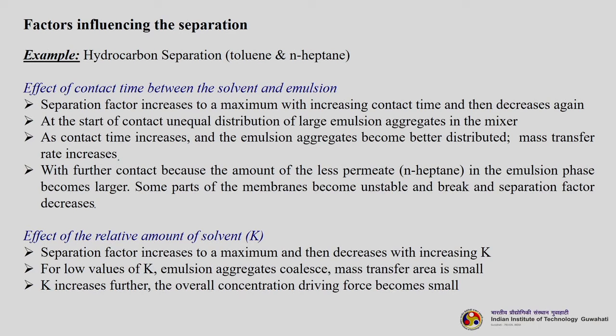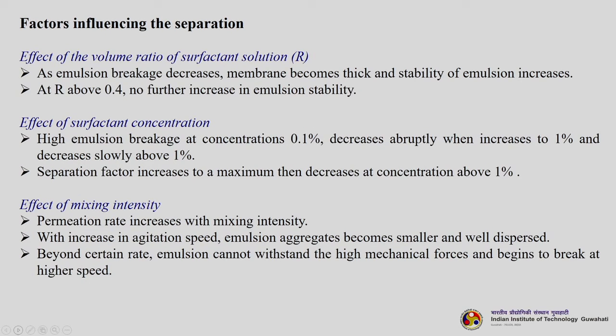So, effect of the relative amount of the solvent. Separation factor increases to a maximum and then decreases with increasing K. For low values of K, emulsion aggregates coil, mass transfer area is small, and as K increases the overall concentration driving force becomes small. Okay. So, the next is effect of the volume ratio of the surfactant solution. As emulsion breakage decreases, membrane becomes thick and stability of emulsion increases. Now, at R above 0.4, no further increase in the emulsion stability will be noticed.